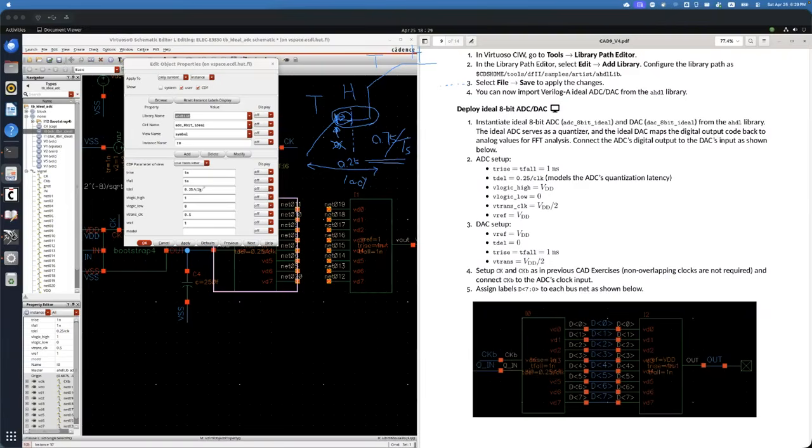Anyway, you can follow this approach for the delay. I will show how the waveform looks. And for the logic high, if your VDD is 1 volt, you can assign 1 volt. If your VDD is 0.5 volt, you can assign that. And this one is half a VDD.